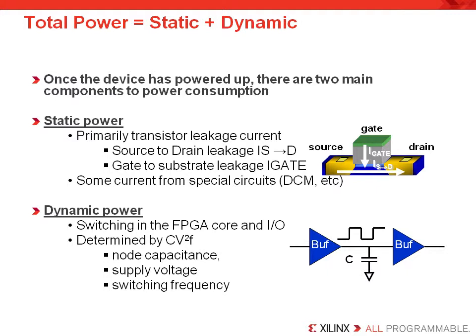Dynamic power is dependent on the switching frequency of the various resources a designer ends up using, and as you can imagine, since there is a lot of logic, this can be a large calculation, particularly since not every resource is toggling at the same frequency or all at the same time. In fact, during normal operation, this can be the most critical element to an accurate power estimate.